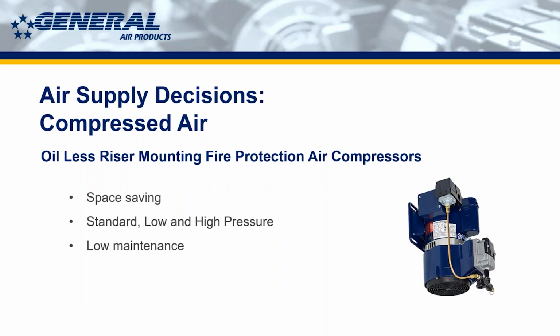If you try to buy a standard pressure compressor and throttle it down at the pressure switch to work within a low pressure valve's parameters, it is not going to go well. The compressor is going to short cycle and be all out of whack, because the pressure switch is not meant to work within that range, say 13 to 18 or 20 to 26. You really need the low pressure compressor.